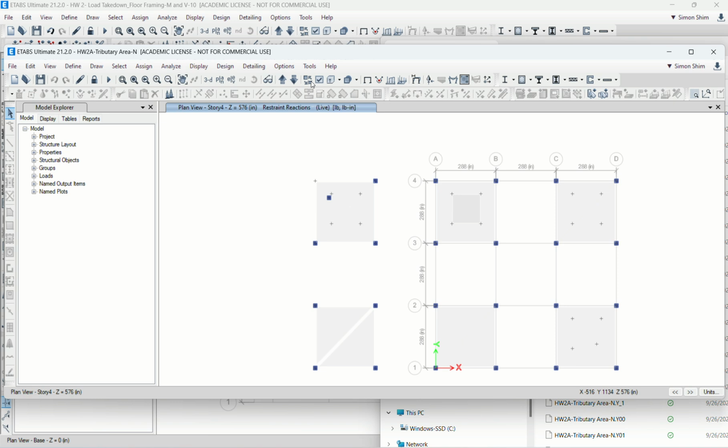Maybe because of the triangular shape, internally they have a different formula, so the uniform load distribution is slightly different, or it's aspect ratio related. So obviously you don't see a different reaction, now we're talking about one story. If you use this method multiplied by 100, the column reaction is quite a significant difference, magnitude-wise.